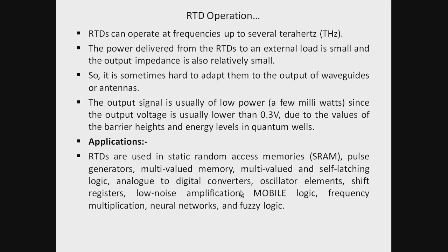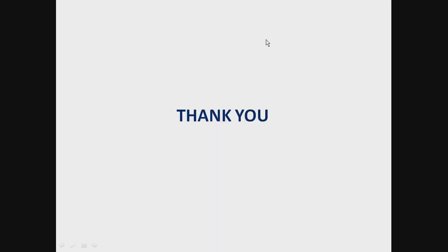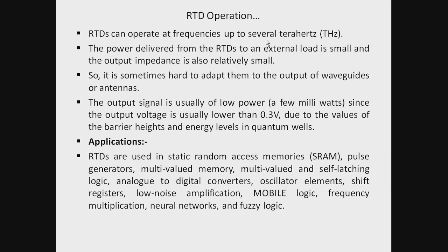So the main peculiarity and feature of the RTD is that it can operate at very high frequencies, of the order of several terahertz. You know what a terahertz is? Such a very high frequency this device can operate at. The power delivered from the RTD to an external load is small, and the output impedance is also relatively small.